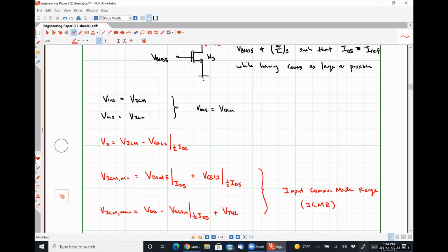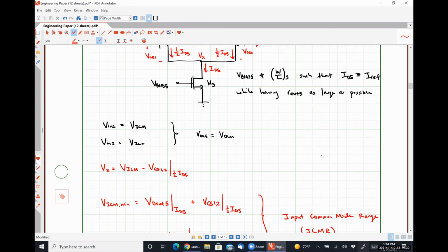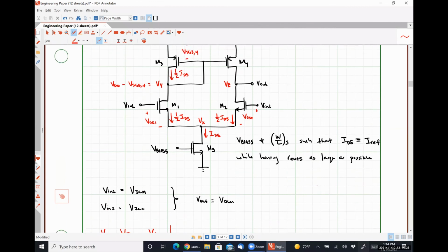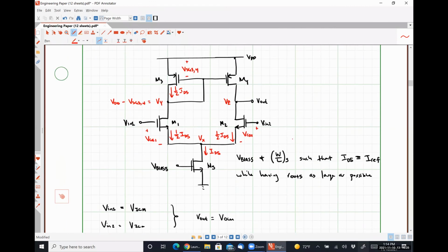So we can actually see similar effects if we allow the DC component of our output voltage to change by too much, right? On the left-hand side, VY is pinned. The node between the drain of transistor M3 and the drain of transistor 1 is at a fixed voltage, right? So M3 will never go outside of saturation unless the amplifier doesn't work correctly.